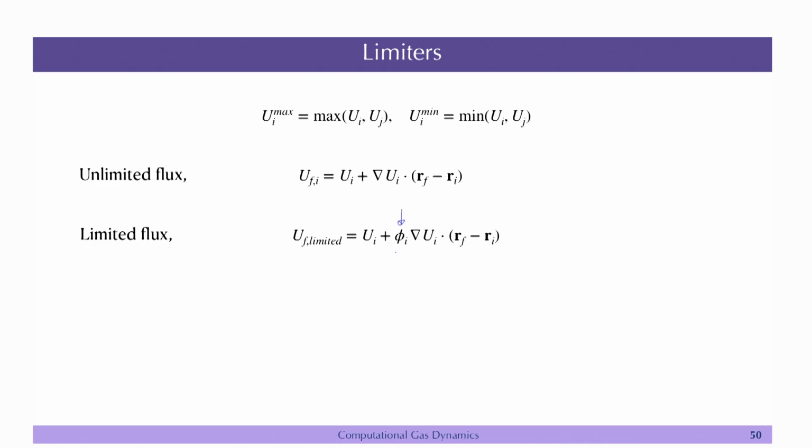What are the different limiters? For the structured grid, either in finite volume or finite difference, we have discussed limiters like minmod or the superbee. Those limiters are useful because they have a clear definition of r, which is basically (u_i minus u_{i-1}) by (u_{i+1} minus u_i), if c is greater than 0.